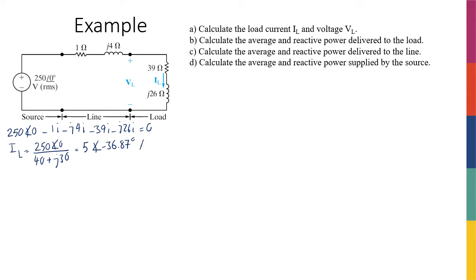Of course, it's amperes, but there's one other thing we have to mention here. The voltage that has been given to us is actually an RMS voltage, right? So I can still work with an RMS voltage, but the current I'm going to get is going to be RMS as well. So I'm going to write amperes, and then in parentheses, RMS. Okay? So that's all you needed to know.